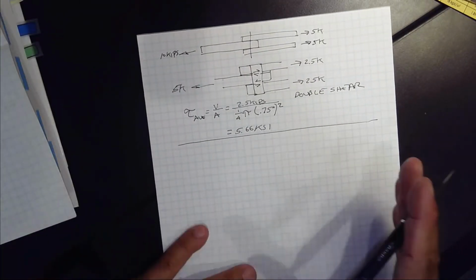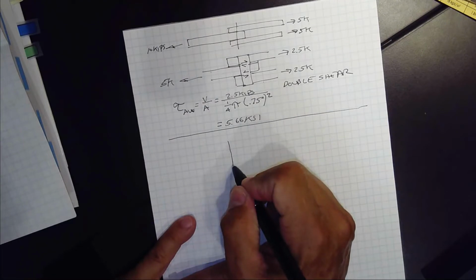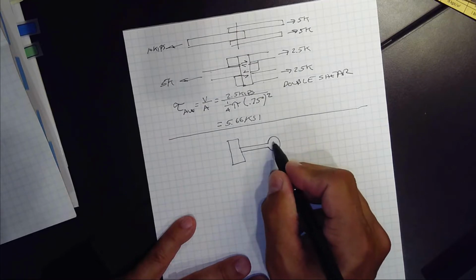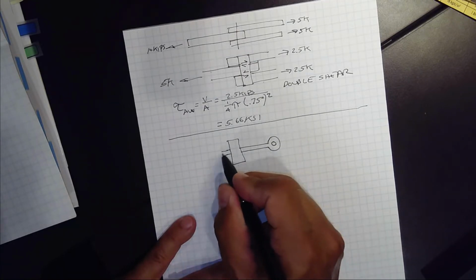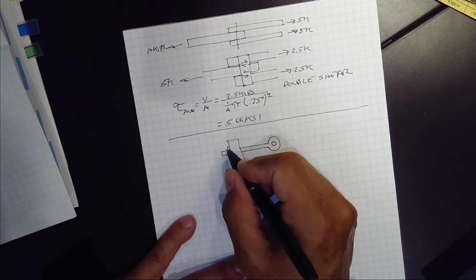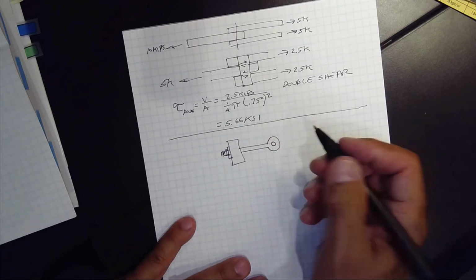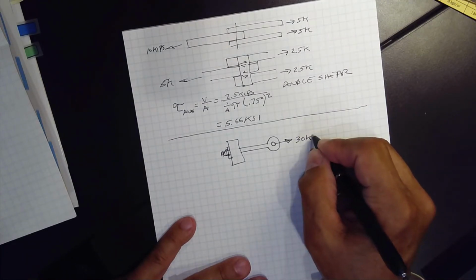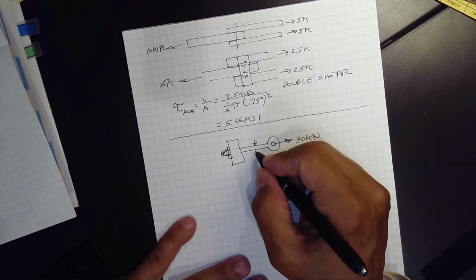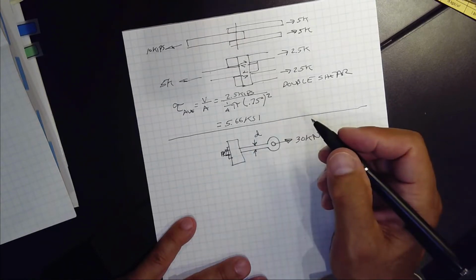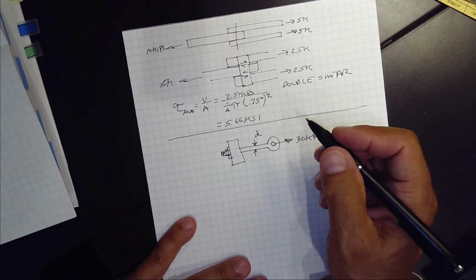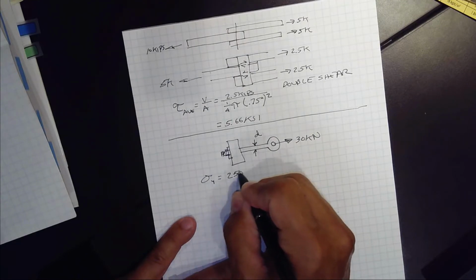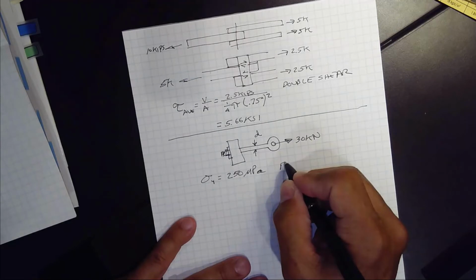Okay, so here we have the block, and here we have the eye bolt coming out. The hole in the eye bolt. On this side, of course, we've got the washer and the nut. And we said that we had a load on this of 30 kilonewtons. And this has a diameter of D. That's what we're trying to determine. So we know that sigma yield is 250 MPa. And we wanted a factor of safety of 1.5.